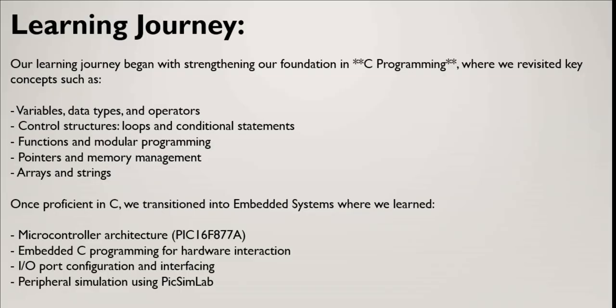After gaining confidence in embedded C, we studied the PIC16F877A microcontroller architecture in detail. We learned about input and output ports and their configurations, internal registers and memory organization, timers and counters for delay generation, and interrupts for handling real-time events.